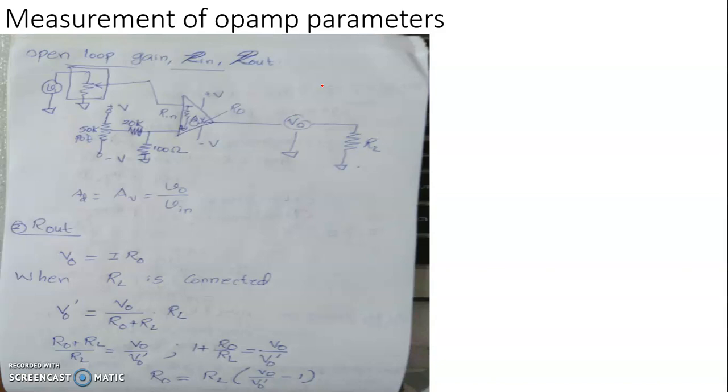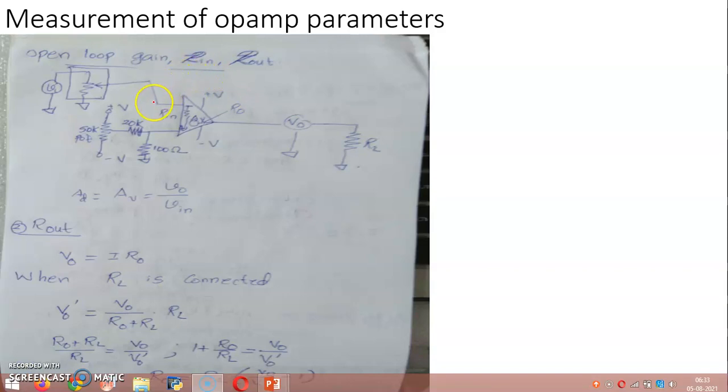And in any calibration measurement, you will have to first of all account for a balancing of the input offset voltage that we often do with the help of a universal balancing technique which we have discussed earlier. In this case also, to measure the open loop gain of an operational amplifier, we make a circuit to operate in the open loop configuration.